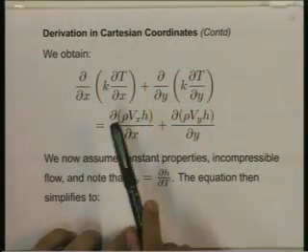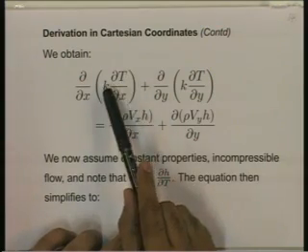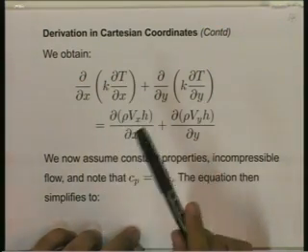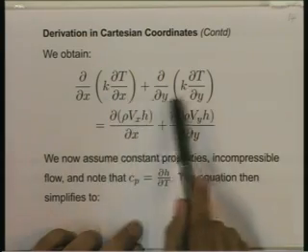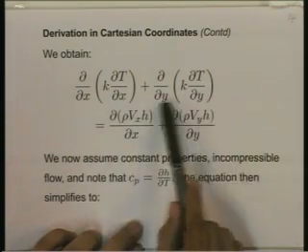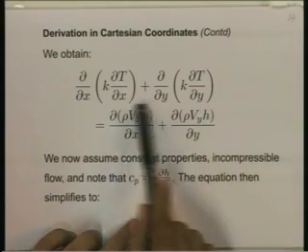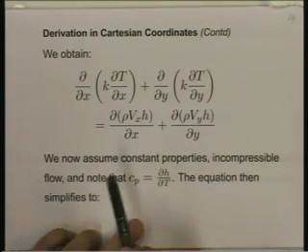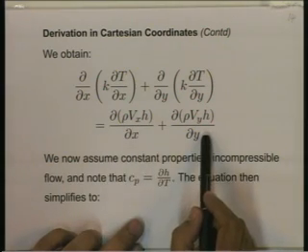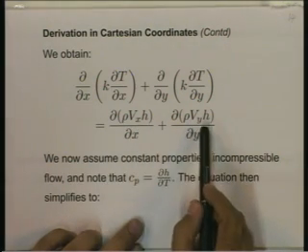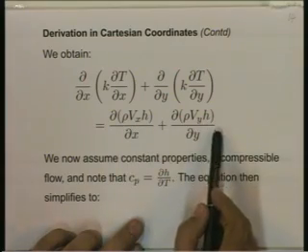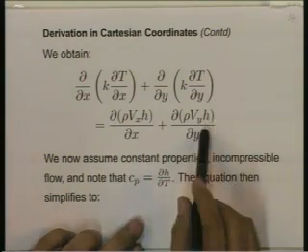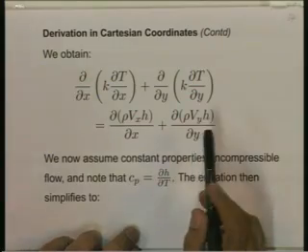On the left hand side of this equation, we have terms containing conductivity and temperature gradients, both in the x direction and y direction. This is the final form of the Q term of our first law of thermodynamics. On the right hand side, we have terms containing Vx, Vy and h. These are the enthalpy outflow terms, the final form in the differential equation of the enthalpy outflow terms.